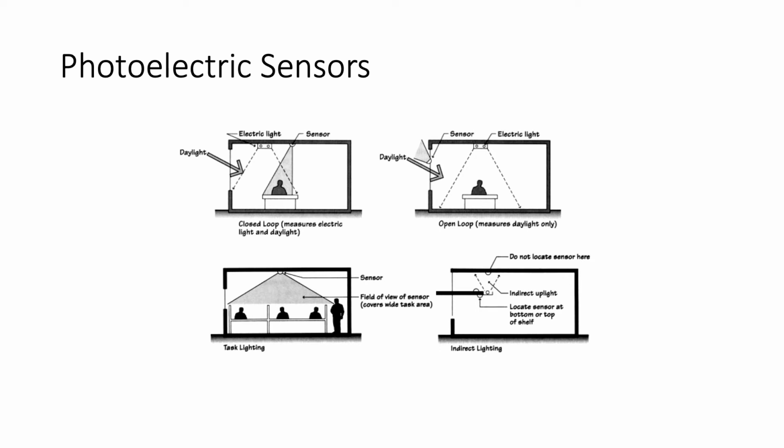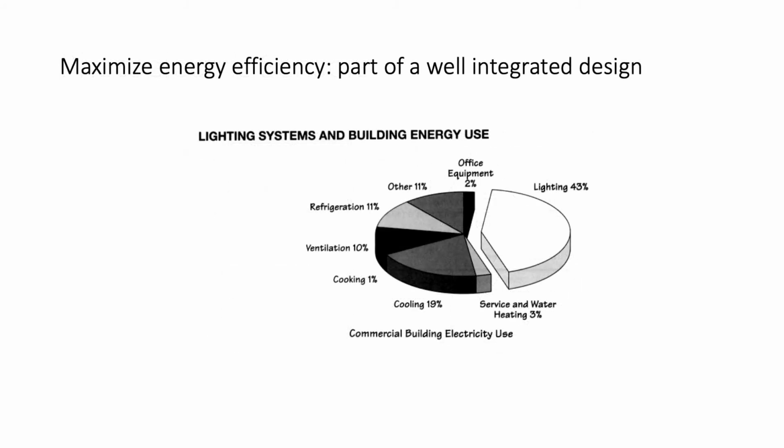There are so many different flavors of these: open loops and closed loops, and also lighting which turns on and off task lighting. You'll want to think through whether the task going on in, say, my office is mostly reading documents. You don't want the lights switching on and off every time a cloud goes by, so you'll want to tweak the sensors in that location. Whereas if it's a circulation corridor, it doesn't really matter. You can probably set those to a much lower threshold for light level.